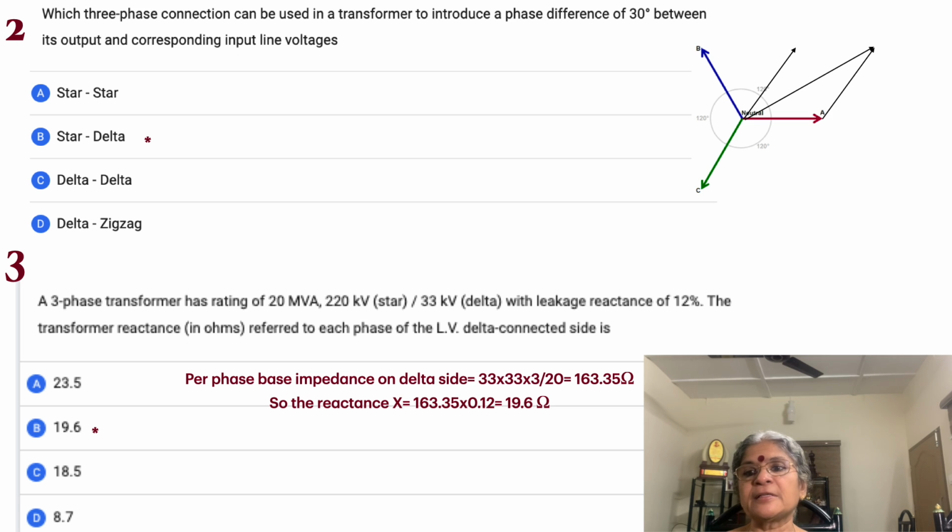A small diagram has been drawn there, wherein the linkage between the star and delta, that is the phase windings, are shown along the same axis, because that's why they are linked together. So if we have VAN, that is VAN on the primary side with the capital A, then VAB on the delta side will be along the same axis when you are representing it in a vector diagram. So when you are taking the line to line voltage of both,